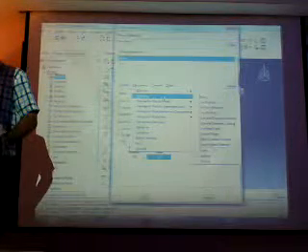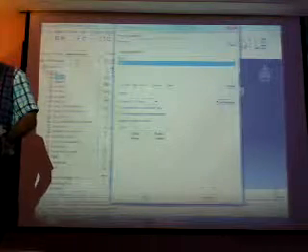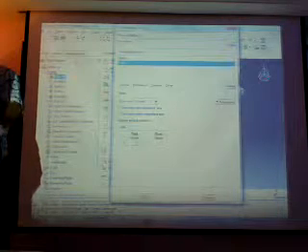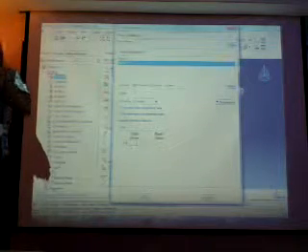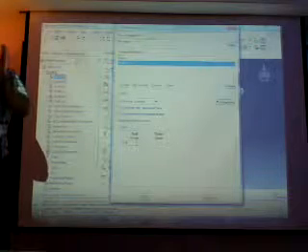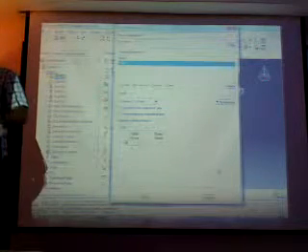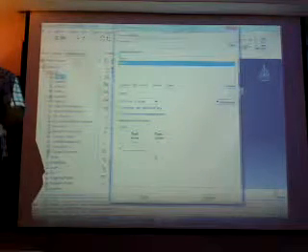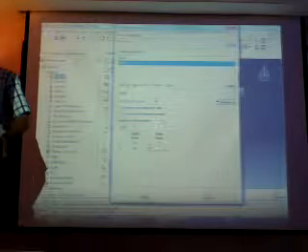And after that, we can define plastic properties according to the stress-strain curve. We can give our data. For example, if you have lots of data, you can copy and paste directly from Excel into this table. The first plastic strain should be 0 in the plastic properties. That's very important. If you don't, it will make an error. Here we just take two data points. That's enough.